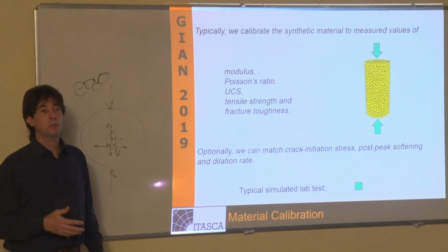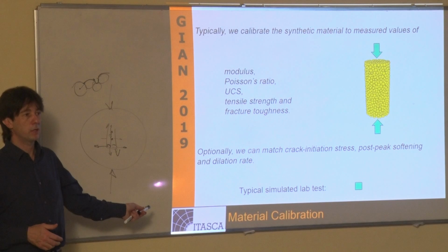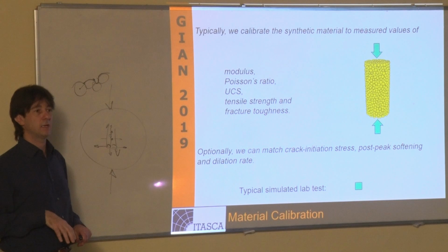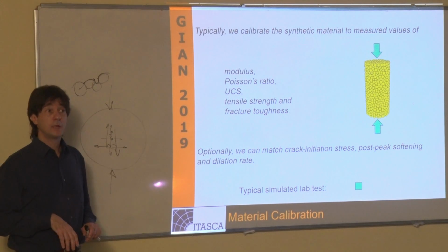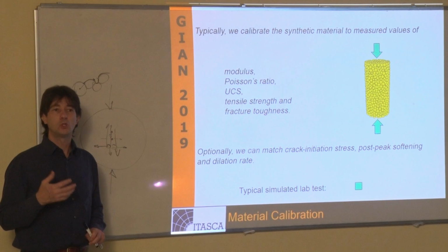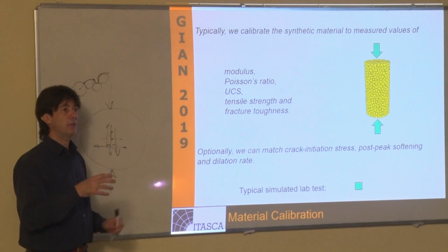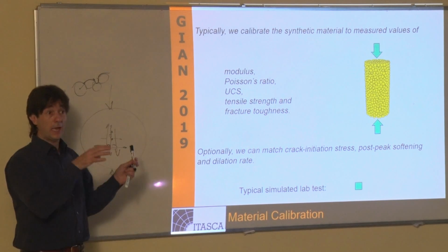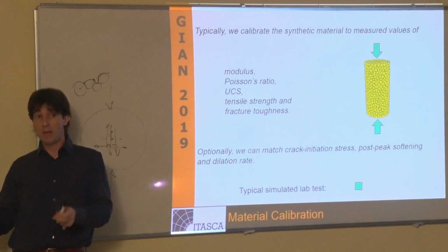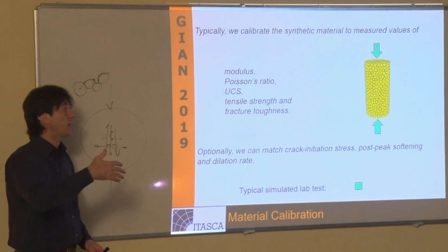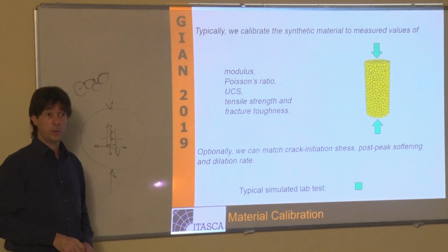Okay? And in micromechanics, the more complex the model is, the more difficult it is and the more involvement is needed from your side. Very often, you have no clue if the model is right or wrong. So you need to simplify the model to check if the set of parameters you have chosen actually matches that simple model. And only at that point can you extrapolate to the larger scale. Okay?